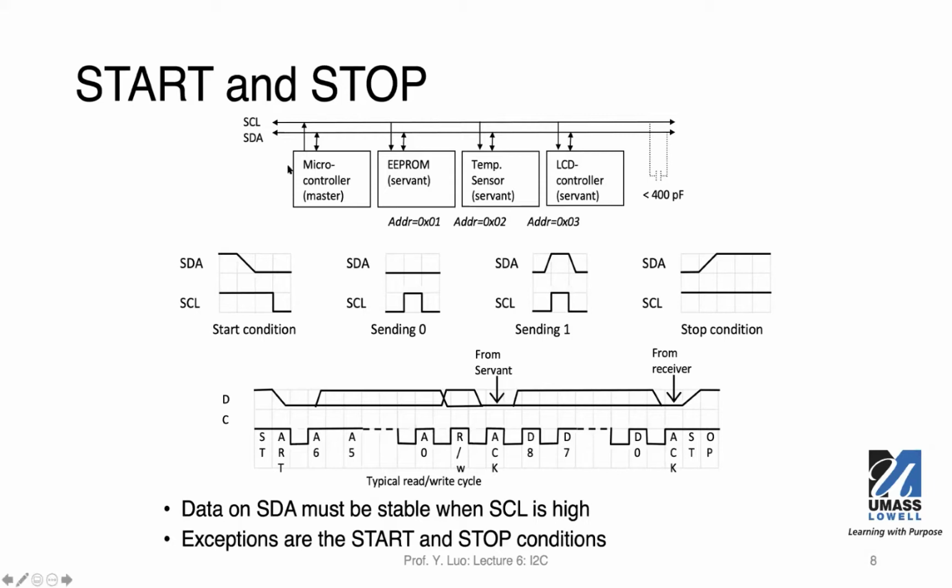The EEPROM? That's right. So the EEPROM is the sender because we read data from this device to the microcontroller. Now, in another case, if we want to control the LCD controller, we're going to be writing some control information from the microcontroller to the LCD controller.